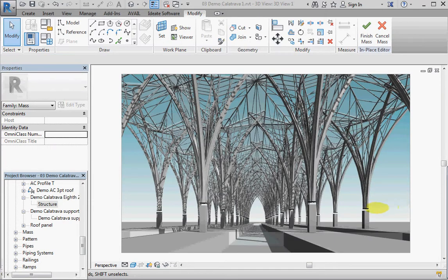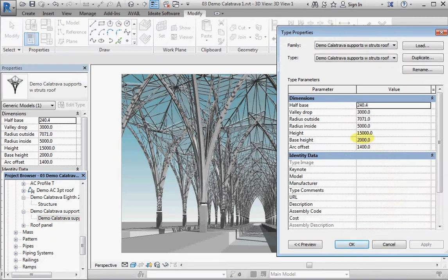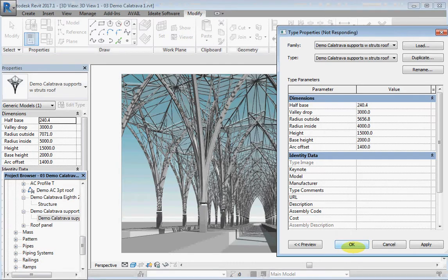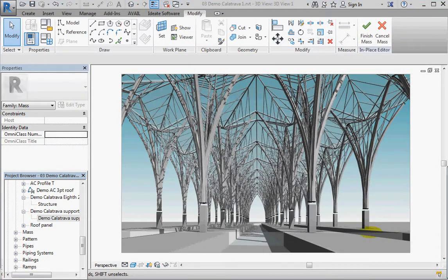Okay, so the arch shape is looking a bit better, but there's something very wrong with the top of the structure, and I think the issue is that the radius of our rig circle is wrong. This should actually be half of the distance between each column, which in this case I put at 8 meters. Whether that's realistic or not, I am not sure because I haven't checked how big the train tracks are. Now we have the overall structural size correct.